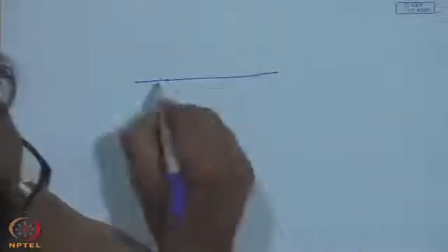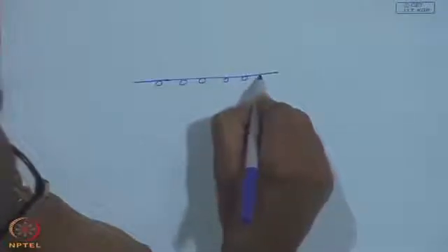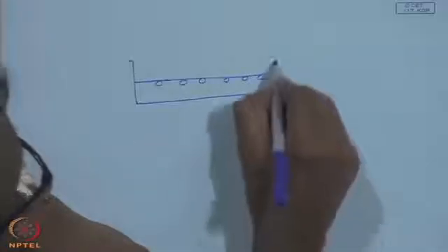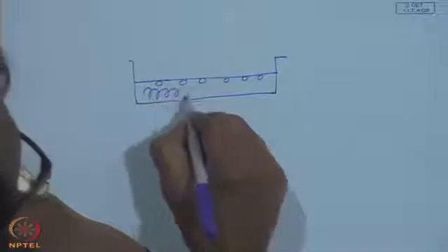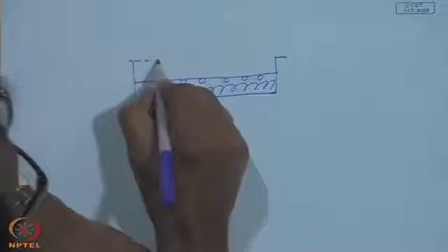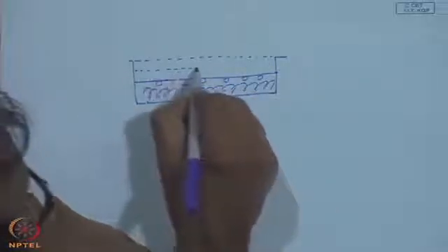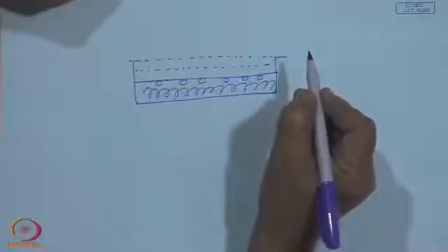Basically, the solar collector consists of an absorber with fluid passages which are pipes, housed in a box, the bottom of which is insulated, so that the back losses are reduced, and there may be one or two glass covers, so that the convective and radiative transfer loss of heat is reduced.